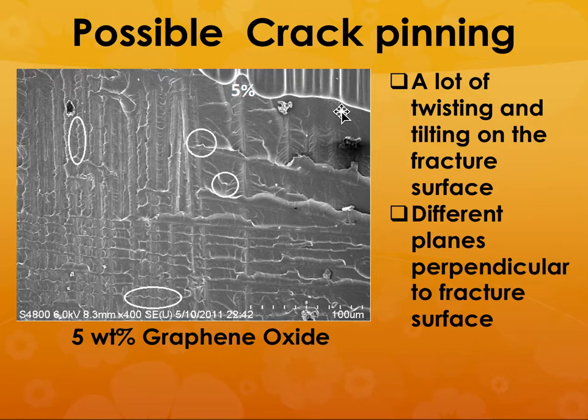So you can see that the addition of different nano additives changes the fracture mechanism on the composite material, especially when you are trying to peel open the composite material, which is reflective of something like delamination. So by adding these nanoparticles, we are able to improve the interlaminar toughness of composite materials.